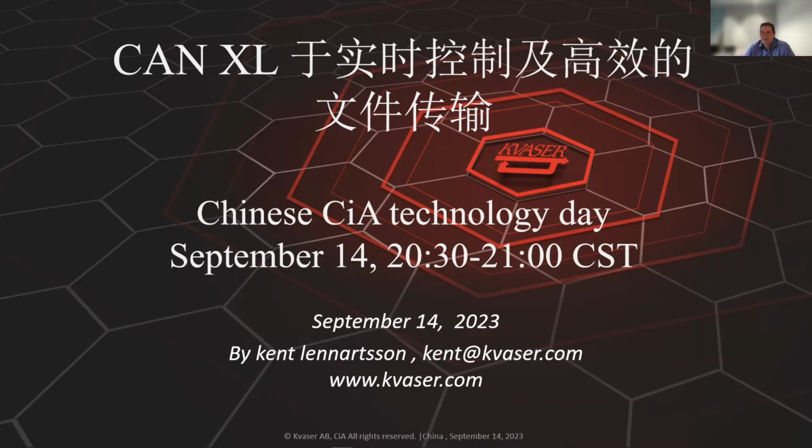We have another one on CAN-FD. We talk about suggesting all CAN-FD nodes use the same sample point settings. Does CAN-XL have the same requirement? No, but Kent, you have already explained, but please repeat. It's suggested to use the same sample point in all ECUs connected to one common system. But for CAN-XL, it doesn't affect it more than that it's not a good idea.